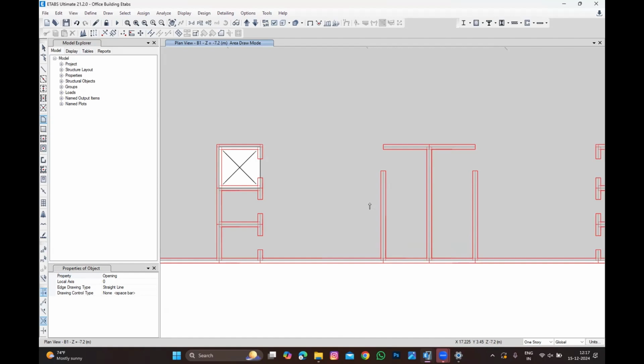But still, what I'm trying to say, in terms of structural wise, in terms of technicality wise, try to model as a slab because this will give you the stiffness. This will reduce the reinforcement. Okay. You may ask, no, the waist slab is going to come later. So what I'm going to say, whatever the load which you're going to assume, wind force and seismic force, this is not going to come into the picture in the initial stage. Even the dead load, the superimposed dead load, live load, only when the building is completed is it going to become the entire load which I'm talking about. Correct? Yeah. So try to model the slabs.